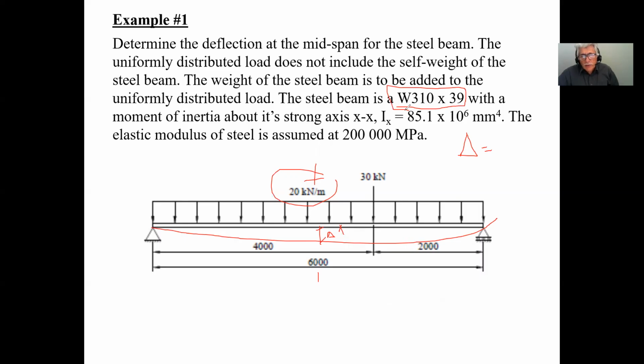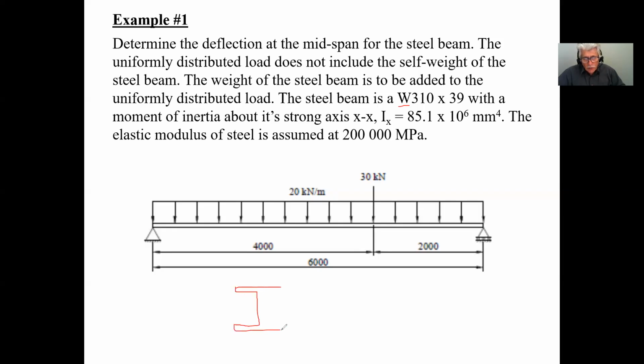Now, I know you guys haven't done any of this. I'm pretty sure they don't do this in construction 1 and construction 2, but I will explain to you what this means, okay? Whenever you see steel, the first letter represents the shape of your profile. So when we're talking about W, we are talking about wide flanges, okay? A wide flange looks like an I, or some people like to call them H's, but we call these wide flanges.